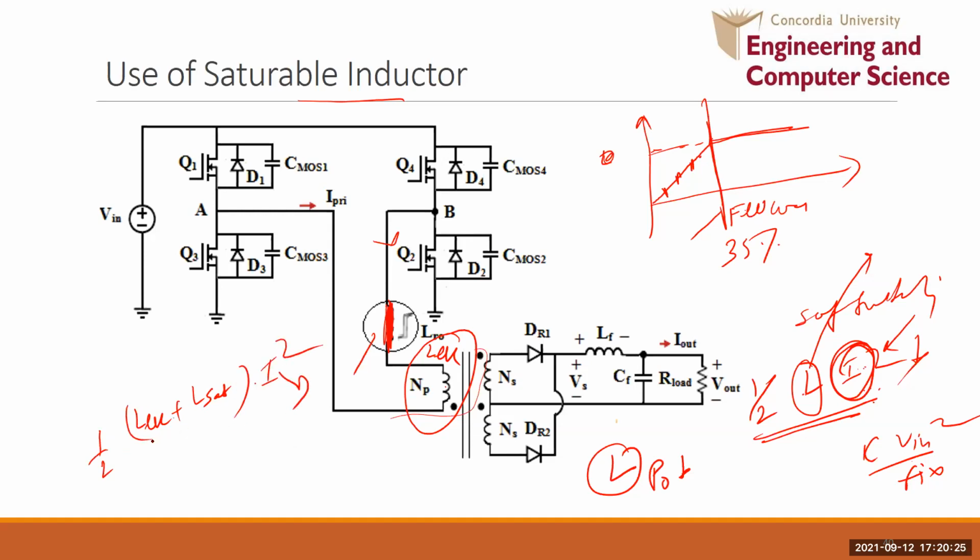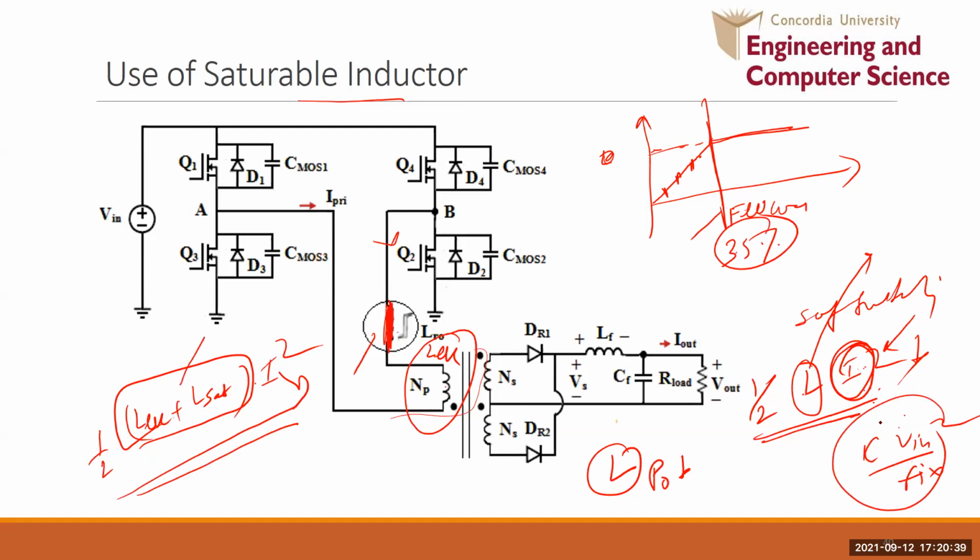This I is low but the inductance is high now, at light load current. Below the cutoff current its value comes into the picture. So half L value has gone up, so the energy has gone up, and this is again able to charge and discharge your snubber capacitors, and you are still able to obtain soft switching at light load condition.